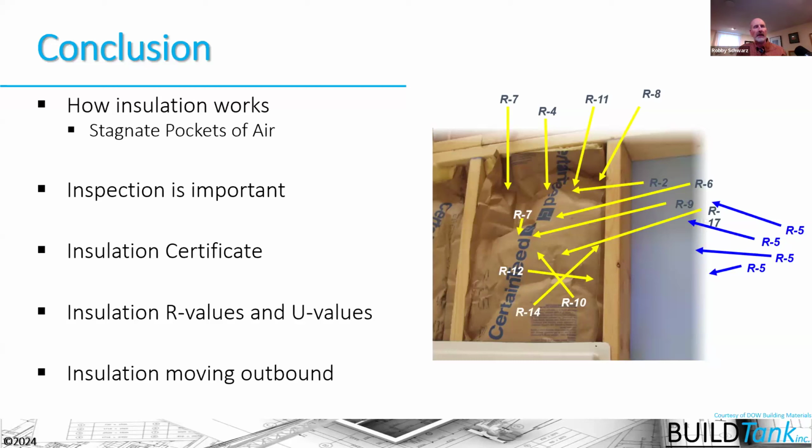And you can see in the picture on the right here that it's all about how well the insulation is installed, and getting the integrity of that insulation and maintaining a consistent R value is achieved often by getting that insulation to the exterior of the building envelope there. Most of the rigid insulations are less susceptible to gaps, voids, and compression. That's not going to happen. So we're going to get a truer R value. We're going to get a better performing house from a comfort perspective, from an energy efficiency perspective as well.